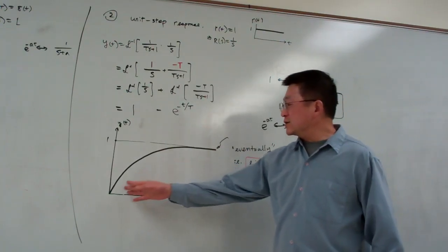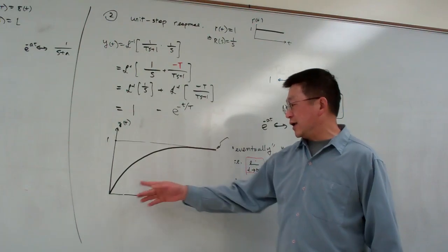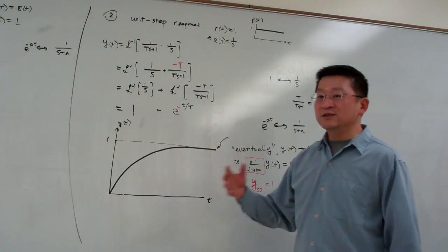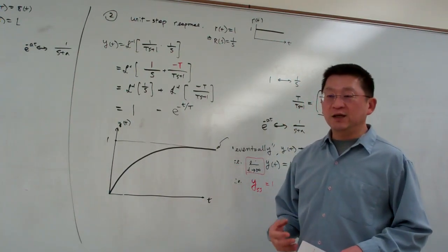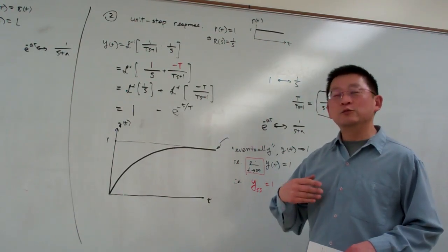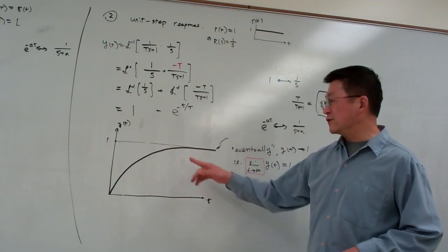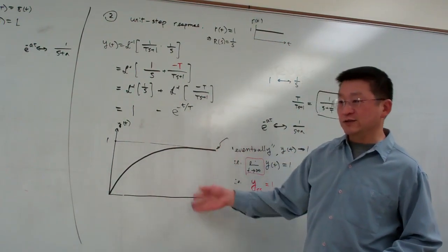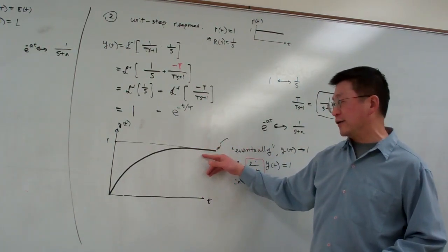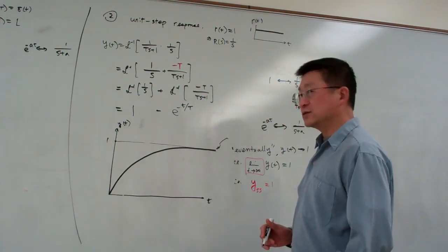And then from the beginning to a certain finite time, that is called the transient response. The transient response is where the system has its initial period, so you need to give the system time to respond to a certain level. For this response of the first order system, we see there are no oscillations. It simply gradually climbs up to the designated value. And for the transient response, we have certain features.